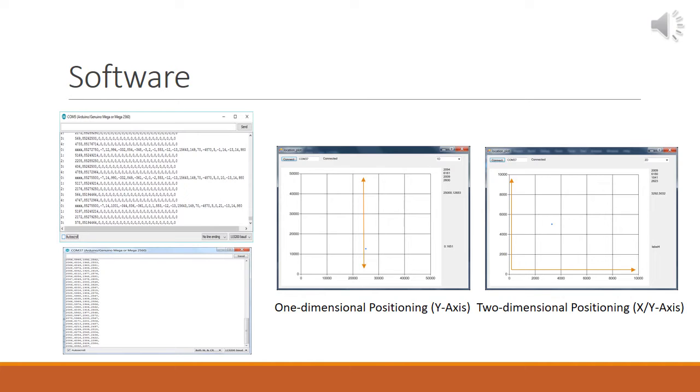And then for the 2-dimensional positioning, I used trilateration between 3 anchors at 0, 0, at some position x0, and some position 0, y, some distance from the 0, 0 node, and then moved around with the tag, and you can see the point move around on the screen in the XY positions.